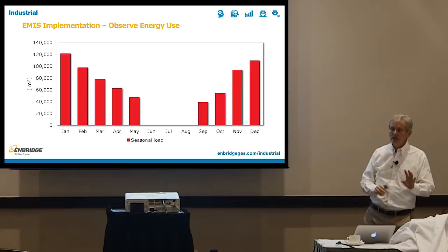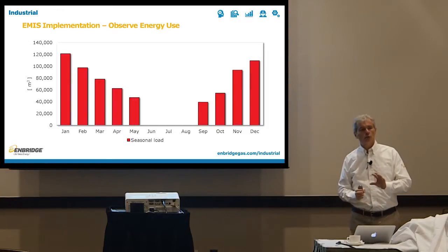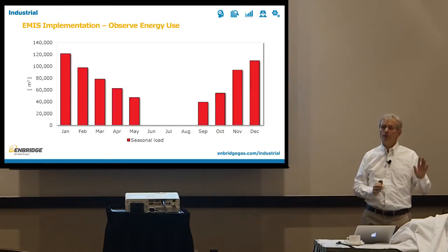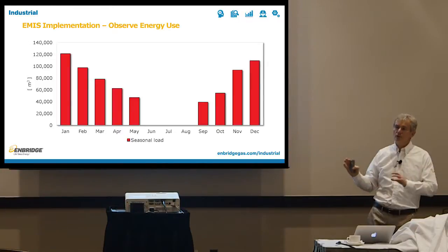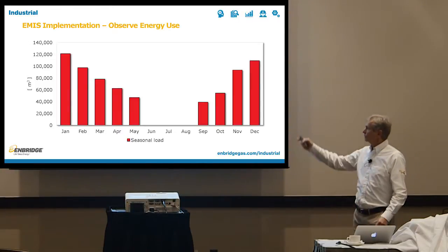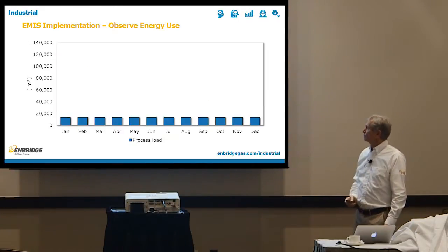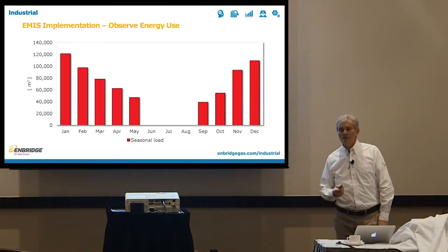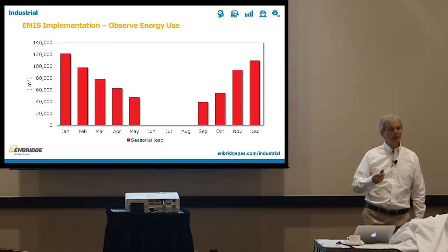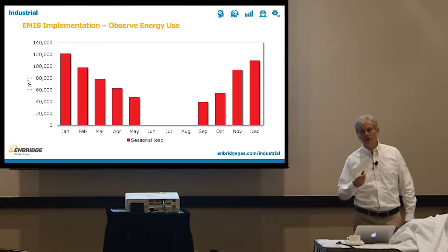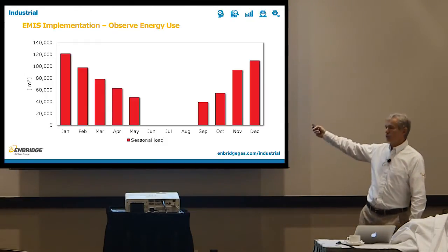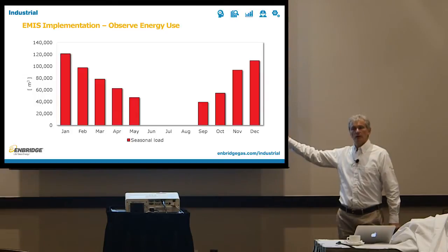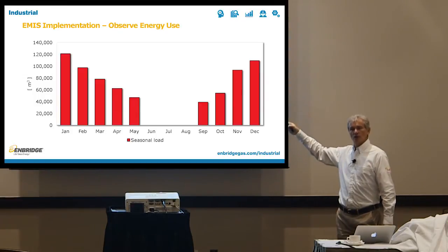So at least that is something you have to do for your energy, before you implement your energy management system. You have to understand what the relationship is. Because in this particular case, this versus this, if I'm strapped for cash and I can only install a certain number of meters and certain energy management parts, I'm going to focus on this load here, because it's going to give me some potential savings later on that are greater